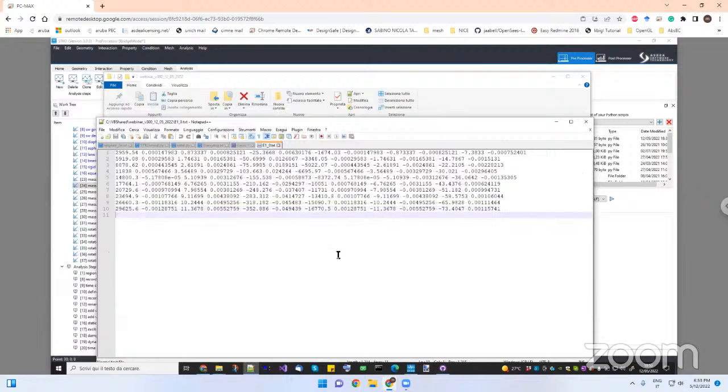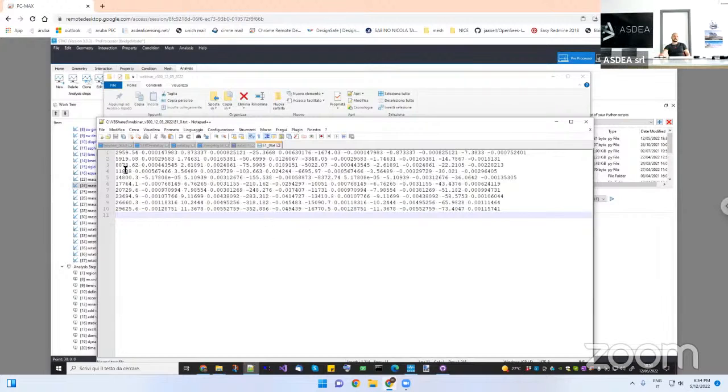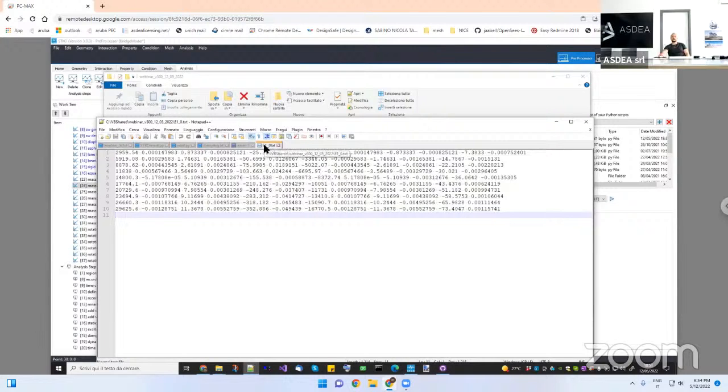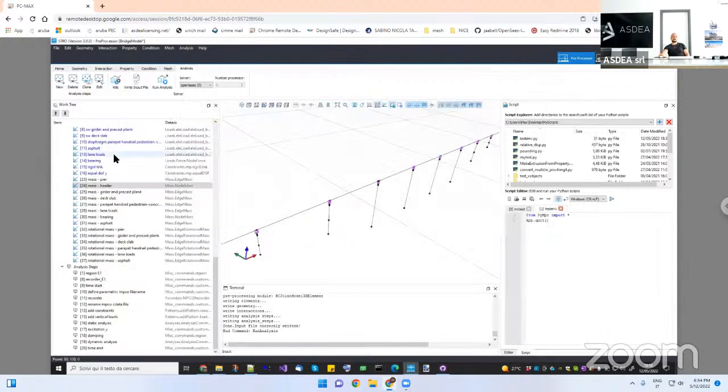Yeah. This is exactly what I do, but I did it just checking the IDs of the mesh. The advantage of this approach is that you don't need to know the element ID. You just need to create a selection set in STKO. Or for example, let's see what happens if I remesh it.